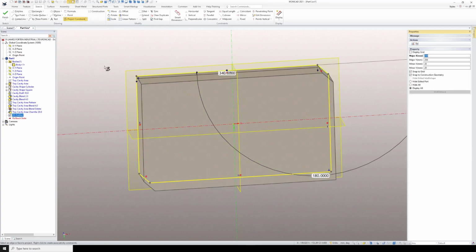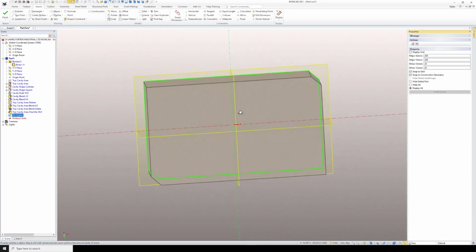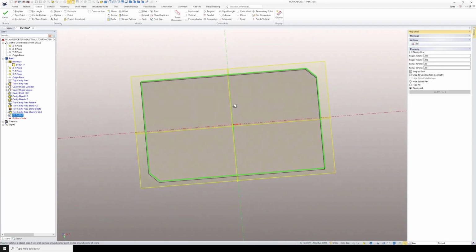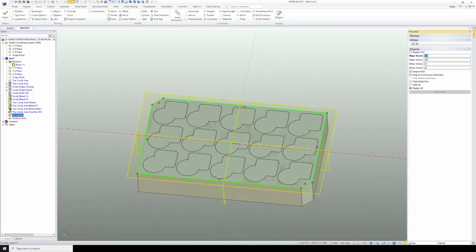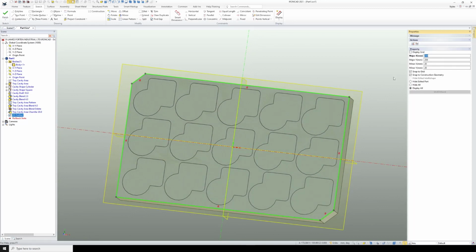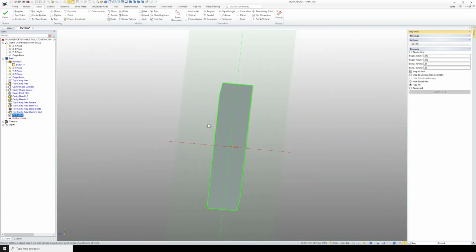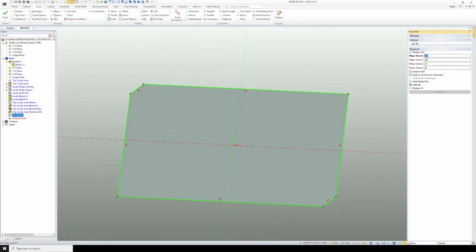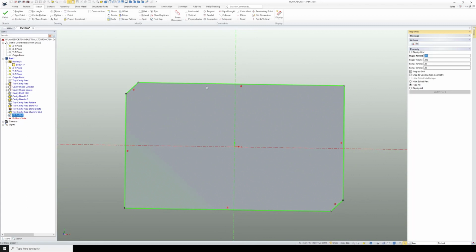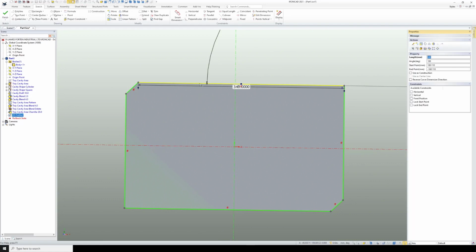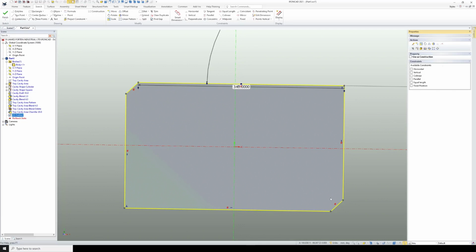And so I press the escape key to finish. And you'll see that there's some green lines that have been projected into my sketch from that geometry. And on the right here in my properties panel, I'm just going to select hide all, because I don't need to see the other geometry within my sketch now. Now I'm just going to do a double click on one of these lines, not too fast, not too slow. Try again. There we are. And it's selected all of the lines.